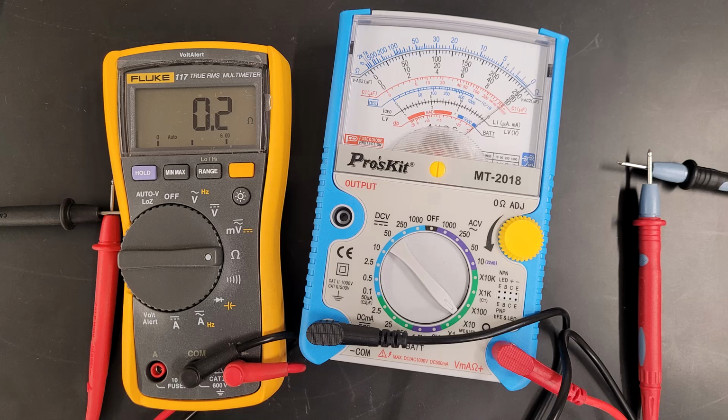Same is true for a maximum value. If you're trying to peak something at maximum, the needle may stay pretty much pegged at maximum. You can tell what that is. There's a kind of a lag, a delay in the time for how fast the needle can move. So it tends to be that it shows maximum and minimum values easier than a digital multimeter.